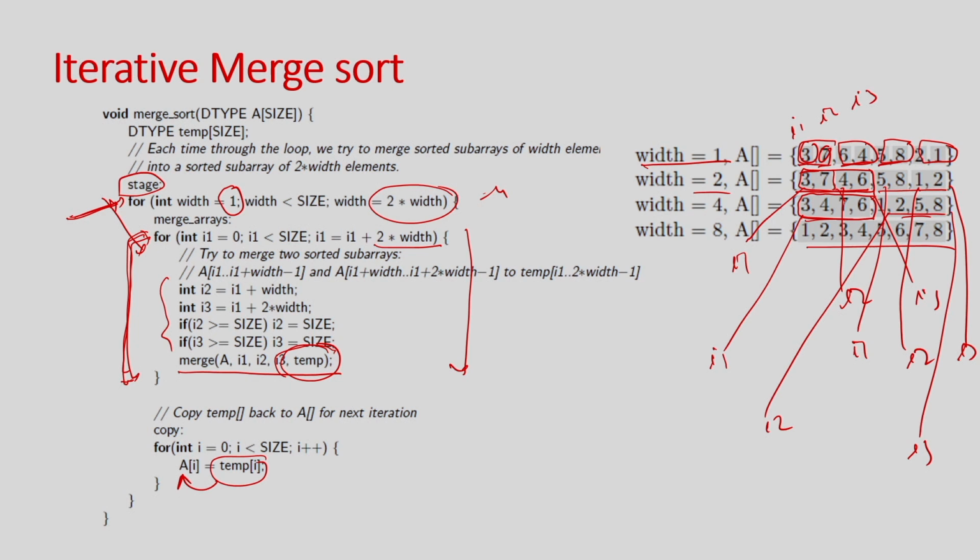Here you can fix the size, because once you run something you can fix the size. The example I have shown is for 8, but you can create it for any size. But when you synthesize, you have to specify the size, because dynamic arrays are not supported. You cannot have hardware which can execute size 4, size 8 and so on. It has to say that this hardware can handle an array of, say, 16 or 32 or 20, whatever it is. It is only going to handle that size. So you will generate the RTL.